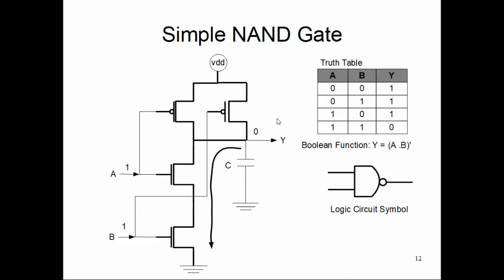So whenever you see this symbol in your logic circuit diagram or any other logic circuit diagram, you can imagine under the hood there are like 4 transistors for one simple NAND gate. Okay, there are 4 transistors, 2 PMOS, 2 NMOS on this. Now continuing on the same